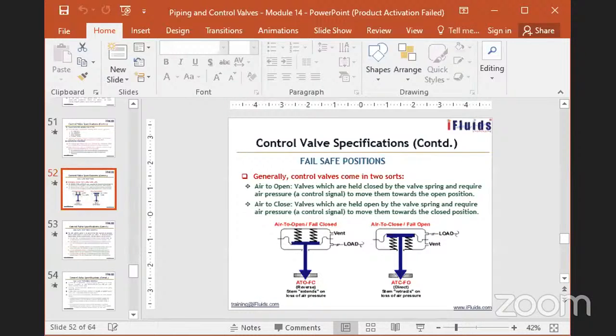Yes, next one. Which are the valves used in processes involving fine or coarse solids and slurries? Slurries we have seen, the butterfly valves are good. Similarly, gate valves are good, but not the globe valve, etc. It will go and mess up the valve inside. So butterfly and gate valves are good.